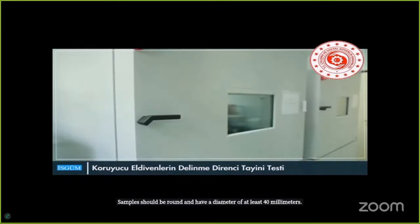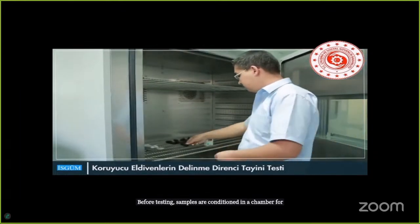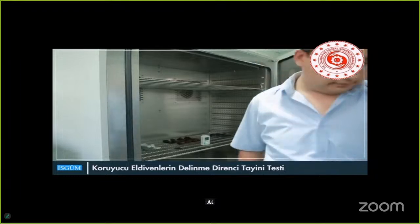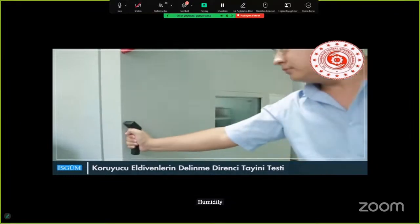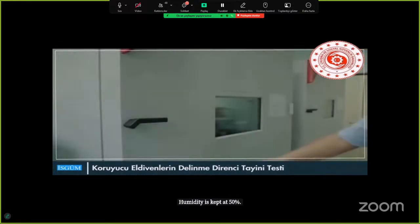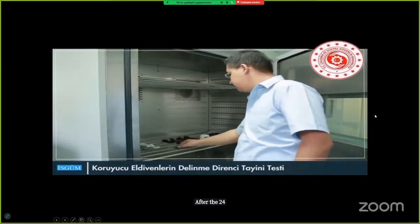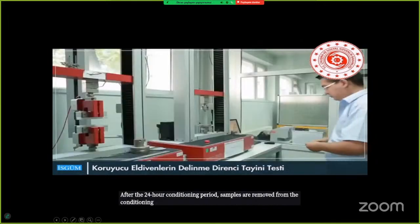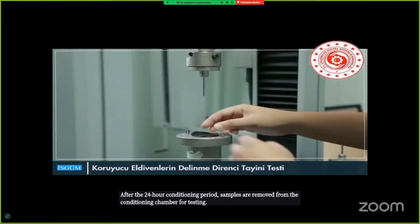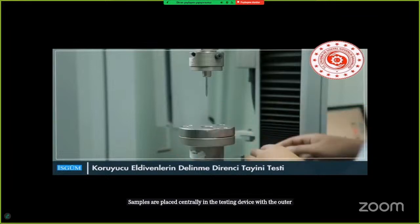Before testing, samples are conditioned in a chamber for 24 hours at 23 plus or minus 2 degrees Celsius. Humidity is kept at 50% plus or minus 5. After the 24-hour conditioning period, samples are removed from the conditioning chamber for testing. Samples are placed centrally in the testing device with the outer surface facing the needle.